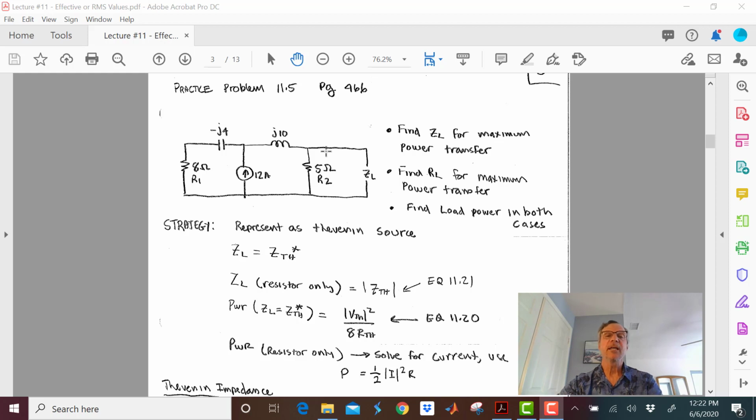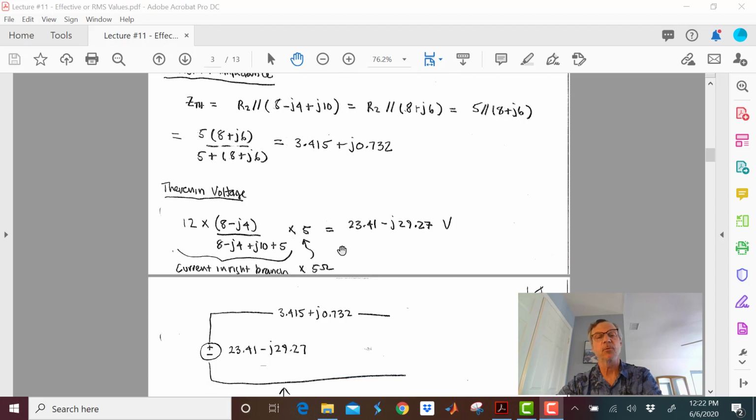So it only covers just right to the left of my dotted line. But how I got to that Thevenin equivalent, I could have got there lots of ways. So there's no unique relationship between my Thevenin equivalent and this current here or this current here. I lost all that when I made a Thevenin equivalent. But remember, my goal was just to represent everything to the left of the dotted line with a Thevenin.